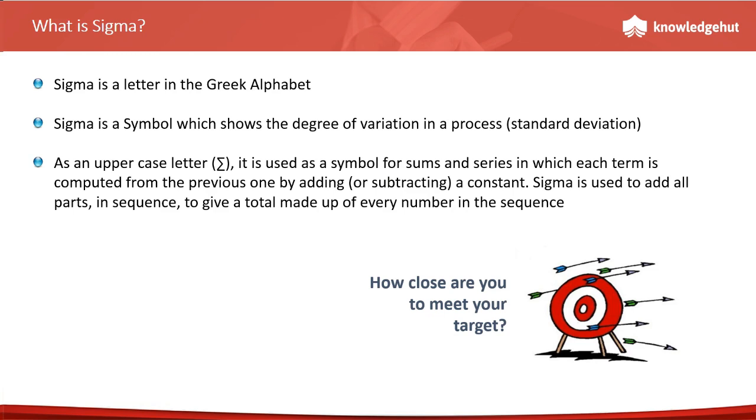Let's take an example over here. Let's say you are a supplier and a car company comes to you. They say, manufacture a nut bolt for me. Now, among the various specifications, let's say the strength of the nut bolt and the diameter of the nut bolt, there is one specification which we are taking over here for an example, and that is the length of the nut bolt. Now, the customer comes over here and says that I want the length of the nut bolt to be 6 inches long, plus or minus 0.3 inches.